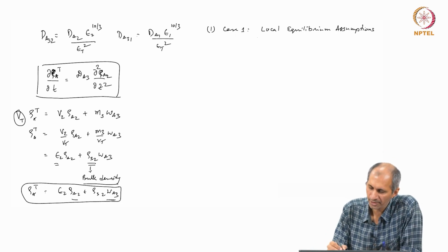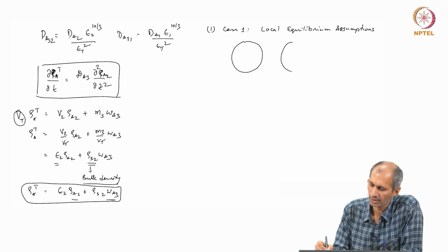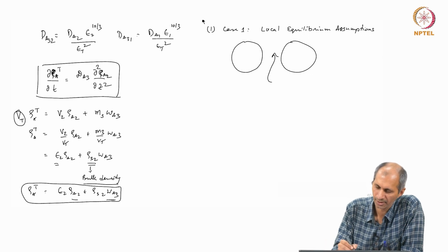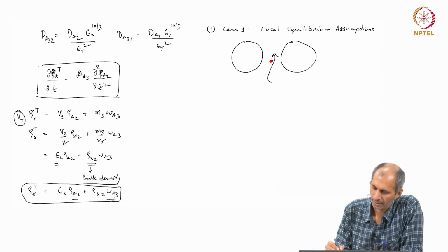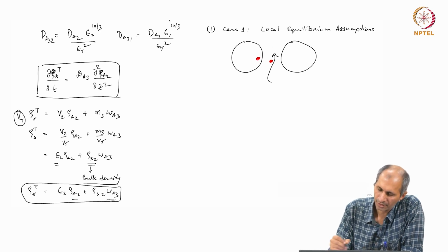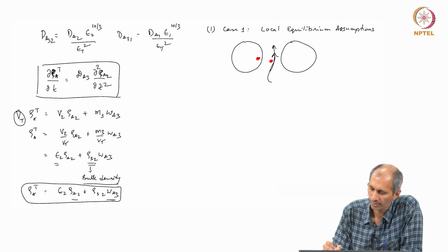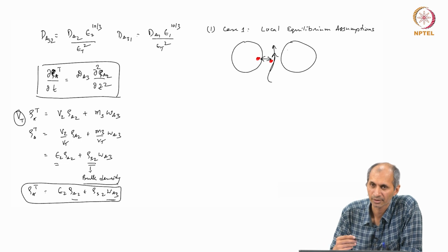The local equilibrium assumption assumes that when a solid is near a fluid, with chemical sitting on the solid and in the fluid, the rate at which diffusion is occurring is of almost the same order of magnitude as the rate of adsorption. So at every point it equilibrates very quickly. The exchange between the solid and the pore water is very quick.